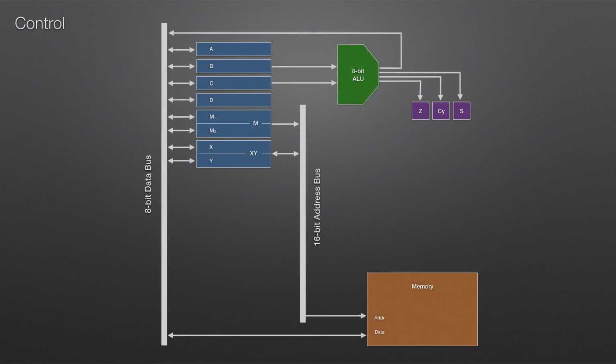So we've now got what is a glorified adding machine that's now got a lot of memory. So far it's not a computer. What we need to do now is add the ability for it to run programs. Programs are just a list of instructions that the computer needs to operate, and those instructions will be held in memory. But what we need is something to tell us where in memory the current instruction is. And to do that we have a program counter.